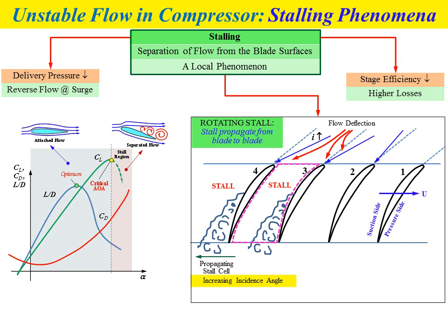However, for blade number 2 and blade number 1, the condition is different, where the incident angle reduces, and no separation flow or minimum separation flow occurs on the suction side of blade number 1 and also blade number 2.